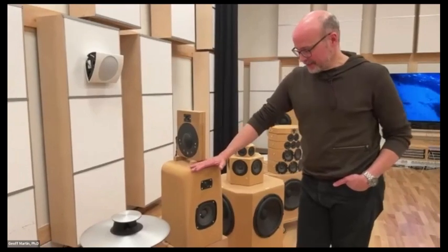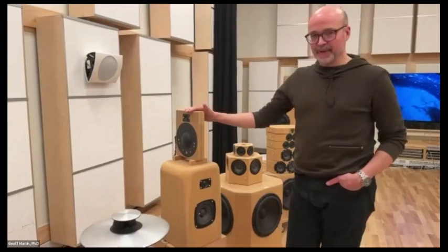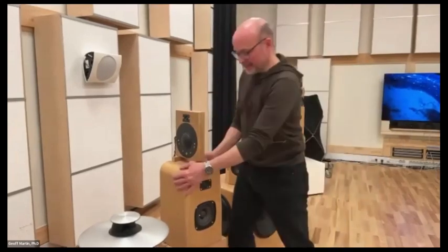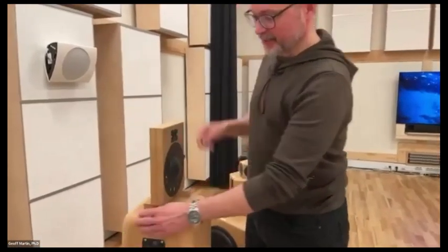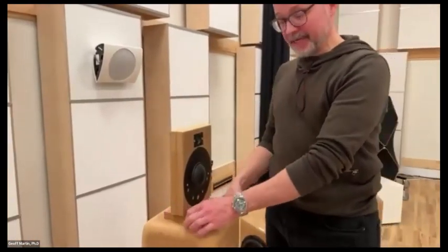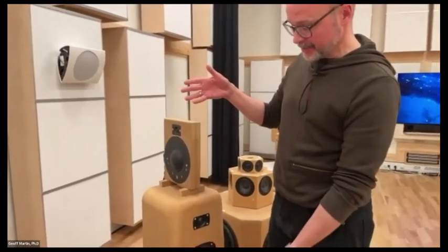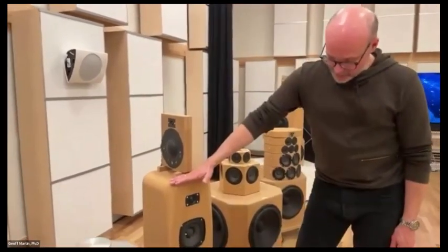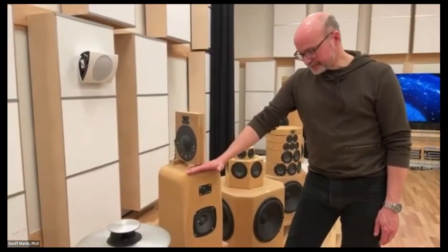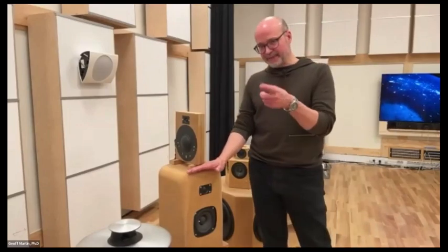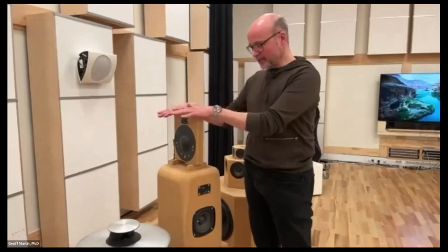And the idea that my colleague came up with was to put a dipole on top. So what we have in the dipole is a tweeter and mid-range and a similar tweeter and mid-range on the other side, all connected individually. So we have, in essence, a 6-channel system. We make the two-way as if we were normal, and we pretend that that's true. And then what we want to do is fill up the power response, that dip in the power response that comes from the crossover, using the dipole.